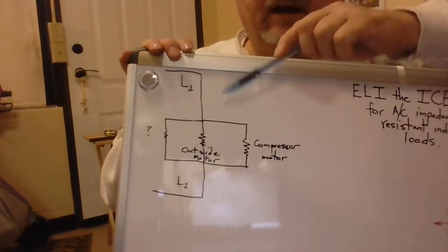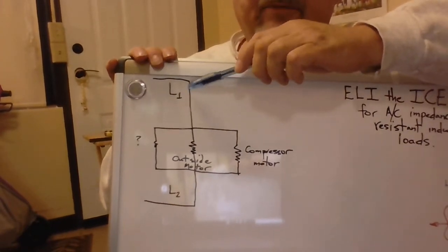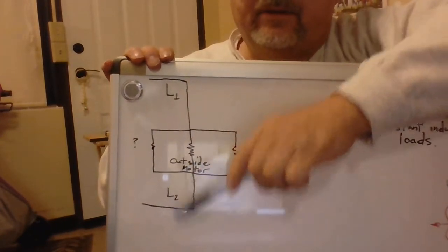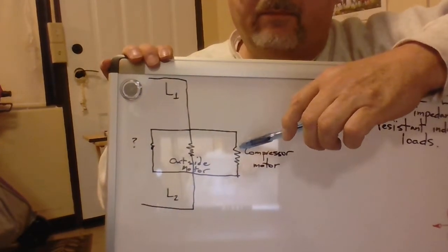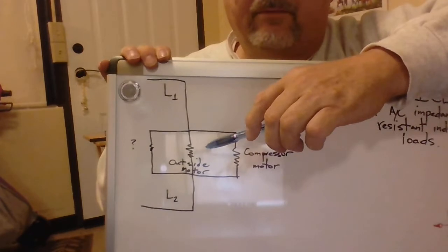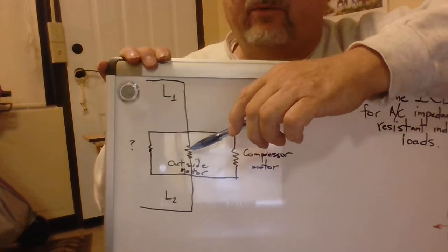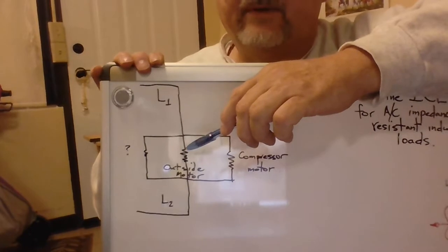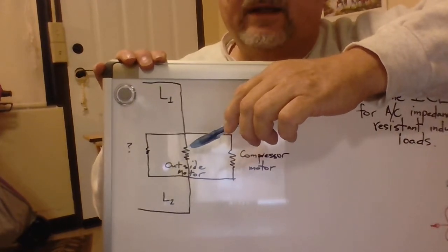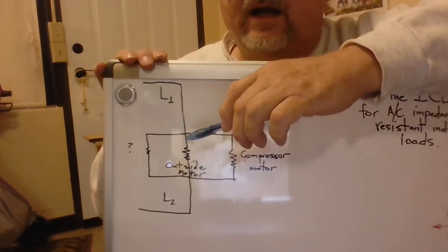So going back over to the series parallel circuit here, on a typical home system like I had, a 240 volt system, L1 and L2, I had the current flow going through the compressor. I don't remember the exact numbers of full load amps. And then the outdoor unit was overamping based on its run load rating, contributing to the possibility that the bearing was overheating, causing the problems. I secured a new motor and replaced it in the fan.